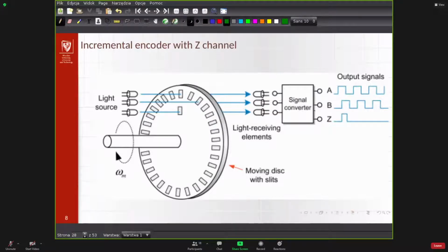So in fact, in processing you can get an additional 2 bits of precision by simply analyzing the four subphases. Yes, so when one is on, the second is off, then 2 on, and so on. So during the one phase between the first and the second impulse from the second tick, you can divide it into 4, so getting 4 times higher precision of the measurements.